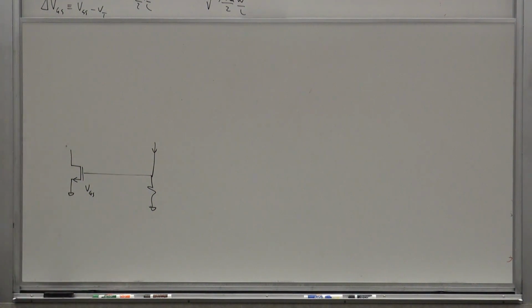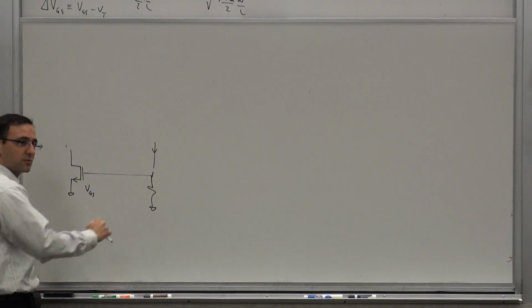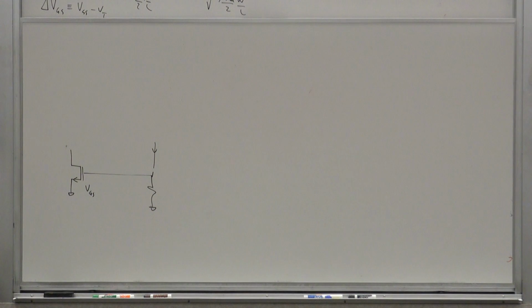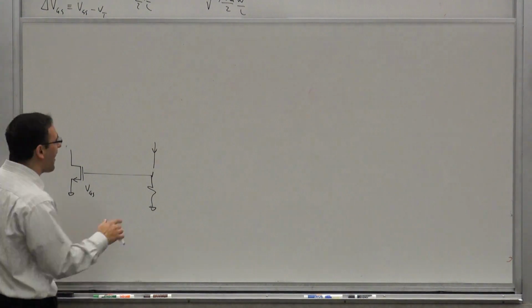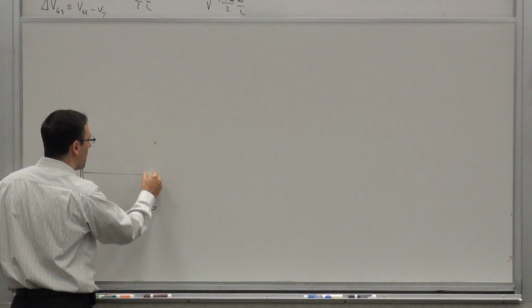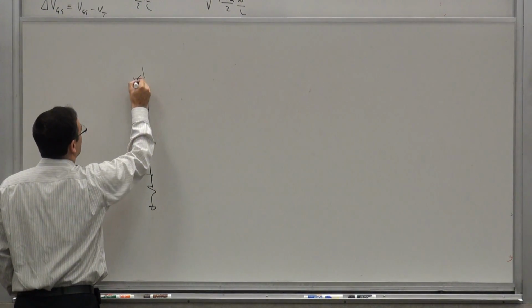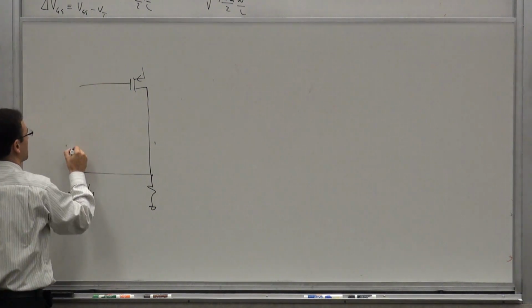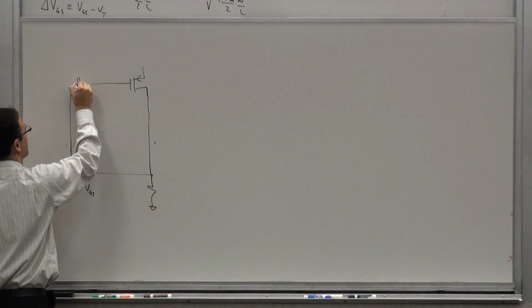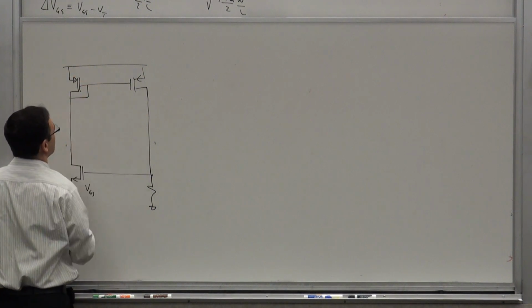You can see this doesn't work because basically if you just leave it like that, the transistor will be off. Because there's no gate current, this will be driven to ground. So I somehow have to bias this resistor, provide this current somehow. So where can I provide this current? Maybe a current mirror. So I can take this current and say, okay, I mirror it. So this is a PTAT current mirror.